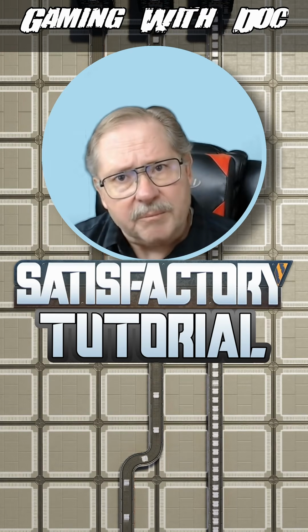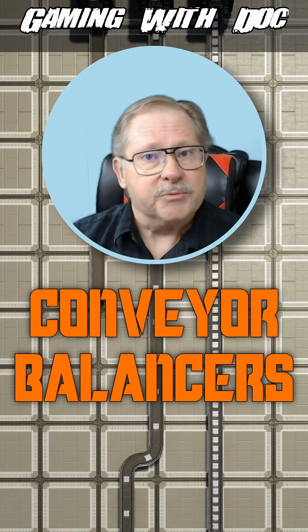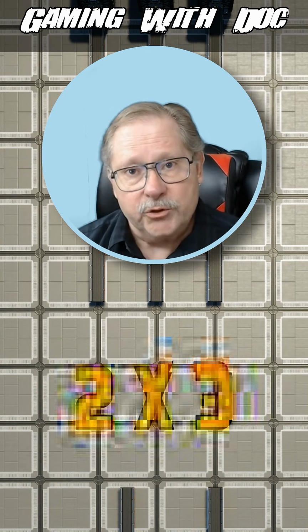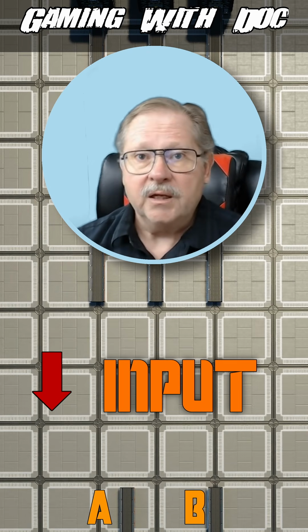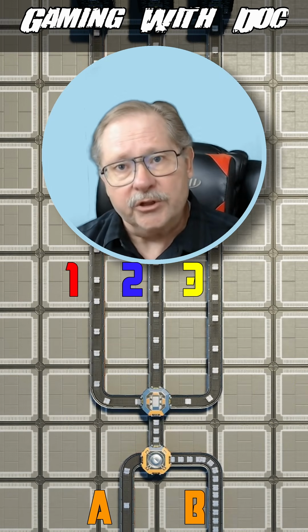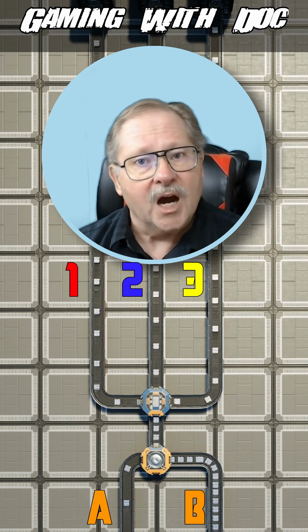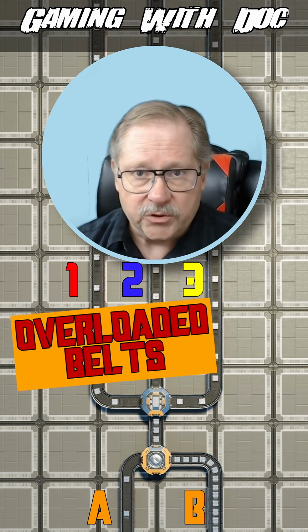Have you ever needed to balance the number of items on multiple conveyors? Conveyor balancers might be an excellent solution for you. Let's demonstrate with a 2x3 balancer, which takes 2 inputs, A and B, into 3 outputs, 1, 2, and 3. The simple solution would be to merge the 2 inputs and then split it into 3 equal outputs. But if the combination overloads the merged belt, you need this second solution.